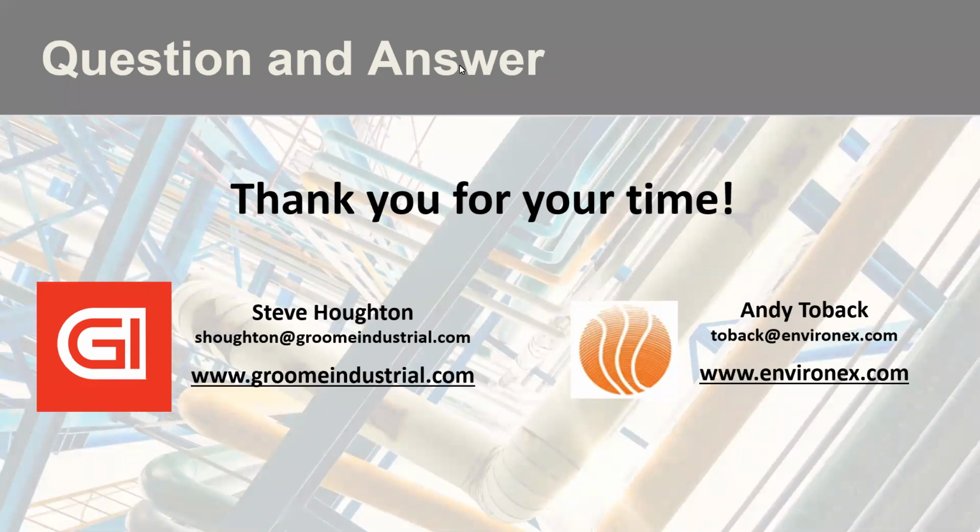Absolutely. Depending on what your NOx conversion requirement is and what your slip requirement is, I'm also possibly familiar with these units, and it all comes down to where are your ports and do you need a permanent grid? Because if the maximum size sample probe that you can get in the duct is 15 foot, let's say your SCR reactor geometry is you have 3 ports on the skinny side, which is like 10 foot wide, and then your reactor is 40 feet long, but you don't have access to put ports in on that 40-foot side. This is a home run scenario for a permanent grid.